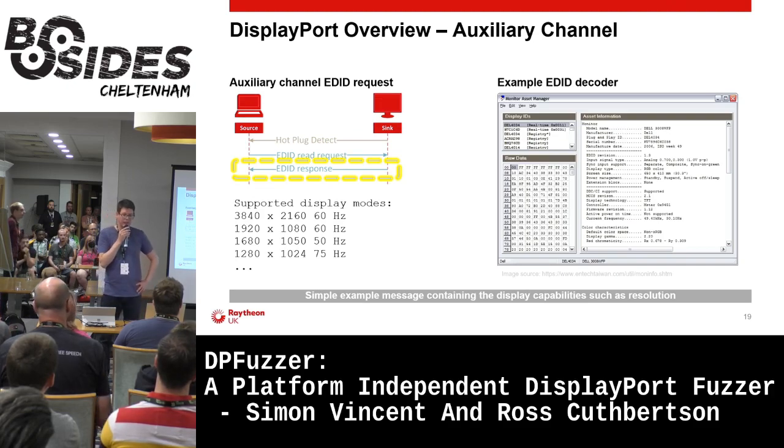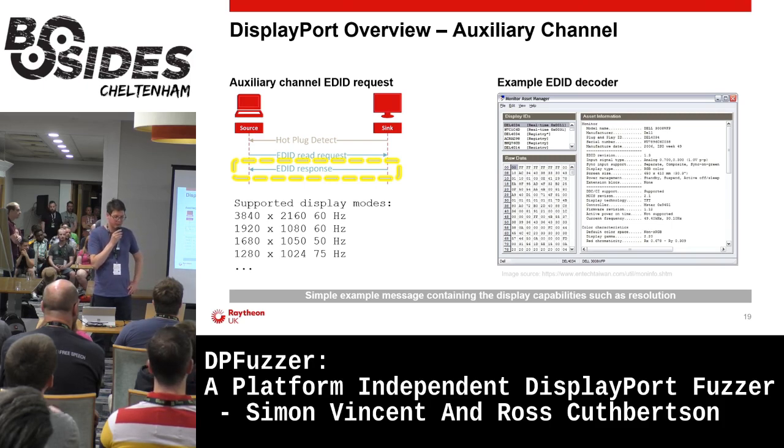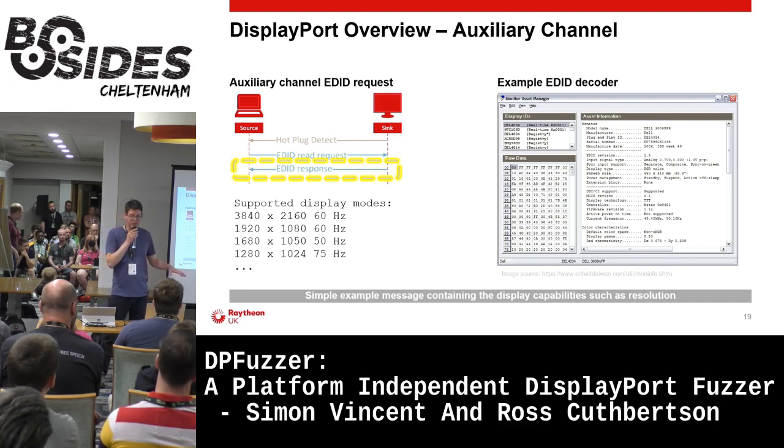So messages are handled at the application layer. Messages like EDID, as I mentioned earlier. And this simple example shows the display capabilities such as resolution are encoded in the data. Messages are typically processed in the graphics driver. And so using the electronics described earlier, we can promiscuously observe messages on this channel between a computer and a display. And these messages provide us with an input corpus for the fuzzer,